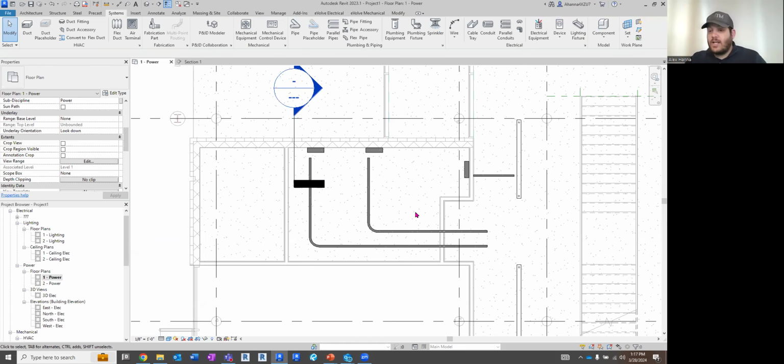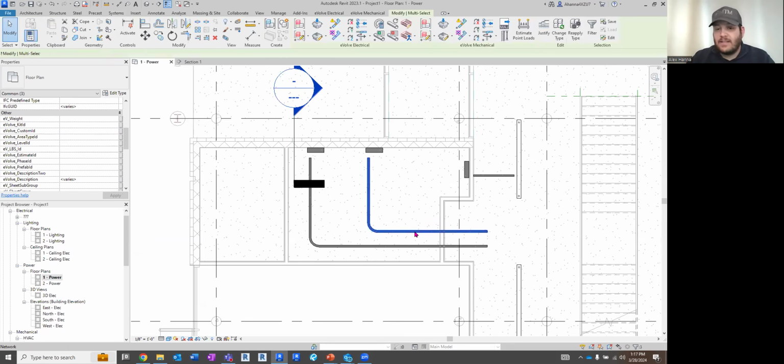So if I wanted to change the whole system, I can use my tab key, which is a multi-select or like kind of a cycle through selections. If I'm hovering over it, both my hands are here, I hit tab key once, it will highlight the whole system. If I hit it again on a larger system, usually it takes 3. With a smaller system, it takes 2. I can select it here.